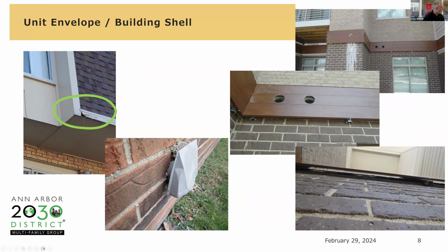So you need to look close at all your surfaces when you're doing your maintenance. Dryer vents or any kind of vent coming out through the brick, that's another spot. Somebody made an attempt to seal up here and it went around the other side, but on this side they didn't. On the side closest to us here, they didn't get that sealed up.